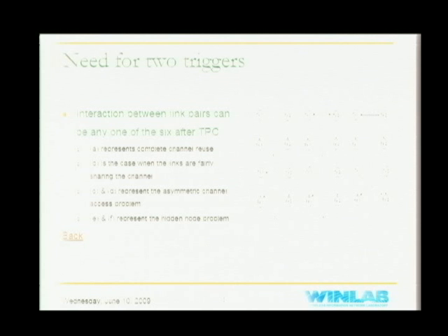So here changing transmit power doesn't make any sense, true, but if you are just monitoring frame loss rate measurements, then the natural reaction to a frame loss rate increase would be to increase transmit power. So it doesn't make the situation any better. So you want to get back to the more optimal case where you still operate at lower power. That is not possible in pure FLR based scenarios or techniques.